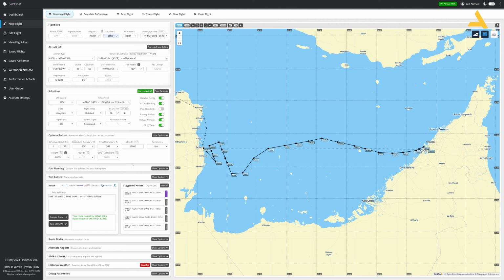But this Simbrief gives you a very good view. Now once you're done with the flight planning over here in this interface, you can generate the flight. But before this, I just remembered one thing, that the units are coming over here, kilograms and pounds. So I've been getting so many questions that the plane only gives the fuel calculation and the weight calculation in pounds. So if you're making a flight plan in Simbrief and your plane has got units in pounds, you can always change it.